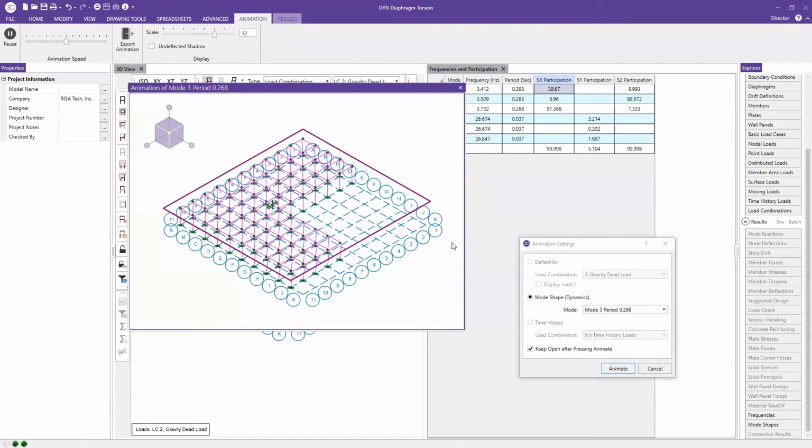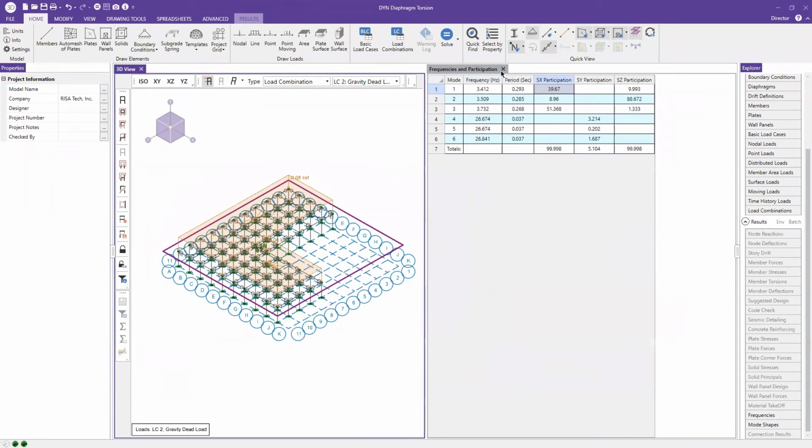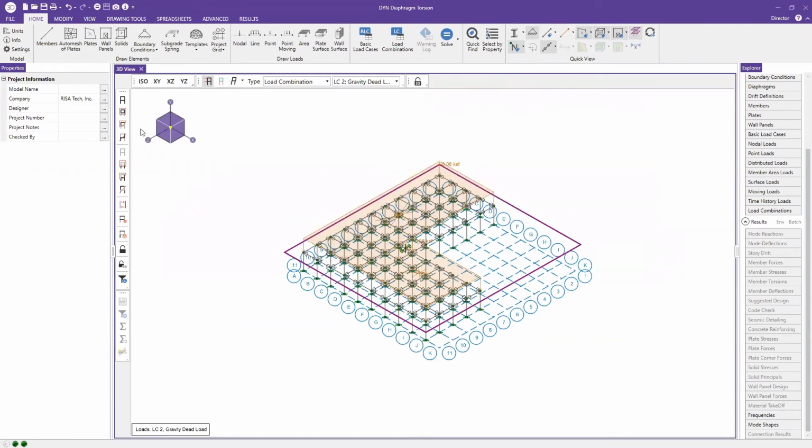So these examples give you a very good case that, as an engineer, you need to make decisions based on the building. If you have a relatively regular building layout, with no horizontal irregularity or vertical irregularity, you can go ahead and use a lumped mass. It'll save you tons of time in solution. But if you have a case like this, you may want to consider using a distributed mass for doing the eigen solution. Now, this pretty much sums up the first model.